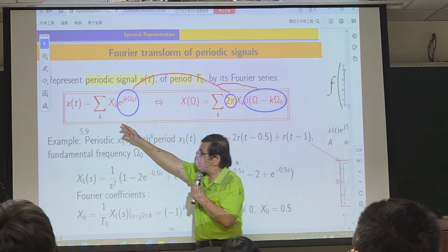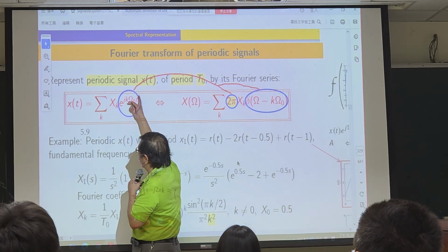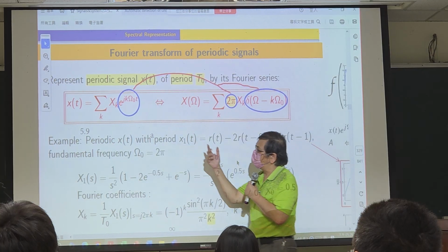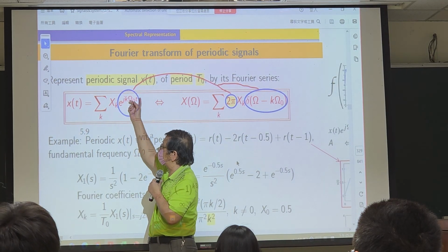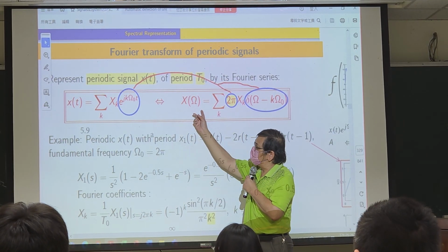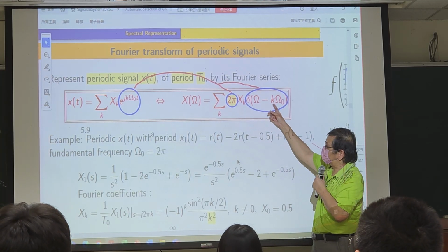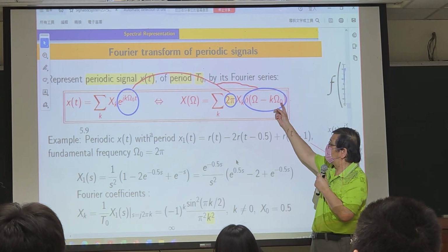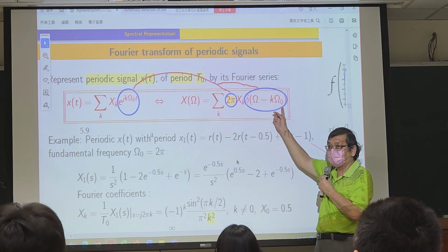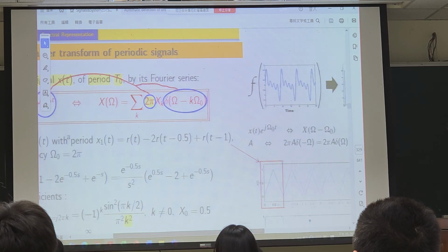So we multiply x(t) by the sinusoidal function, precisely speaking, since this complex exponential function actually is a sinusoidal function. If I multiply the signal in the time domain by a sinusoidal function with frequency k omega_0, then if I take the Fourier transform, in the frequency domain it has a shift, a frequency shift of k times omega_0. Got it? All right? I think I have proven something.